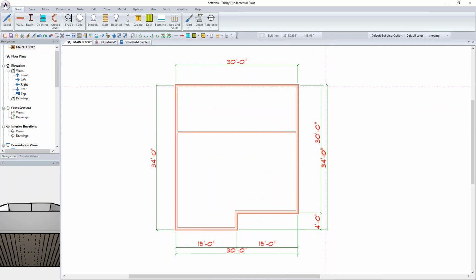As you modify and make changes, a feature that you'll want to run a lot is what's called a cleanup. In my opinion, you cannot clean up or save your drawing enough. Basically, the cleanup goes through and mathematically recalculates your drawing for you, and the save does exactly what you would think it does. You can click this icon at any time, and when you do that, in addition to cleaning up walls to join to one another, extension lines will extend to the dimension strings that they're associated with.